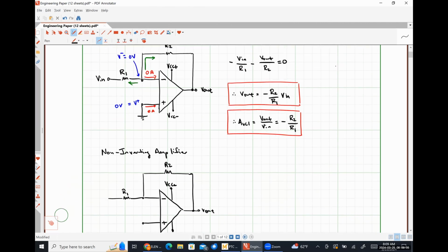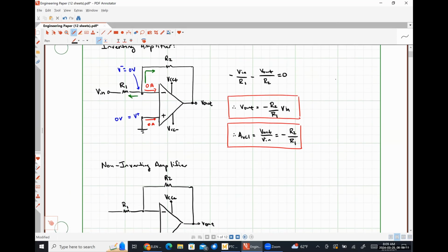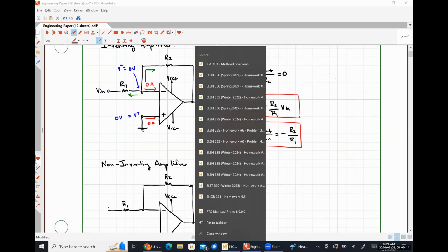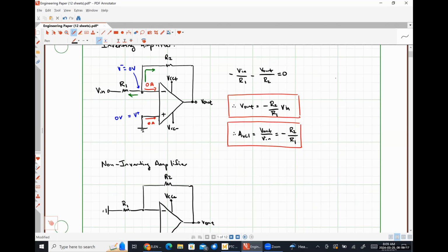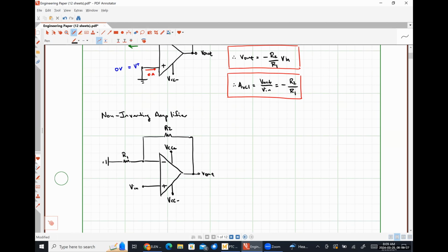So here in our inverting amplifier, we applied our input signal at the left-hand terminal of resistor R1. Now we're going to apply ground there. And in our inverting amplifier, we connected our non-inverting input terminal directly to ground. Now we're going to apply Vin there. So it's literally the exact same circuit, except we're just swapping those two voltages. But we're going to see that we get a pretty darn different input-output relationship. So using the exact same procedure as before, we know that there is no current flowing into or out of the input terminals.